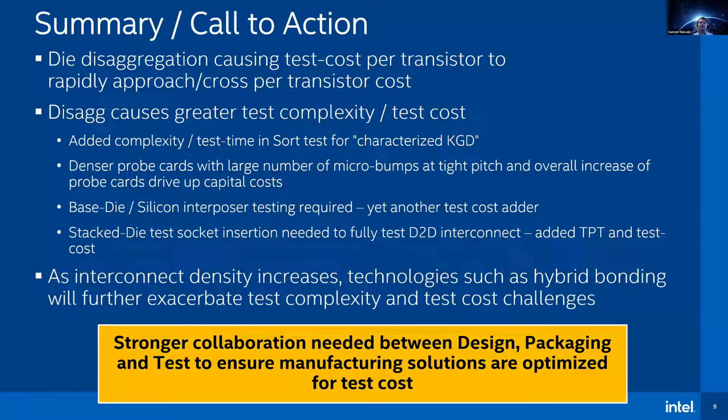Ultimately, you have to make sure that you're able to drive up testability, whether that's engaging with design earlier to make sure that these interfaces and interconnects are testable, and get these standards in, get the connectivity and observability that you need. But there's always this limitation with wafer sort, and then you're going to have to see if your test methods will be reliable at either stack die or final test.